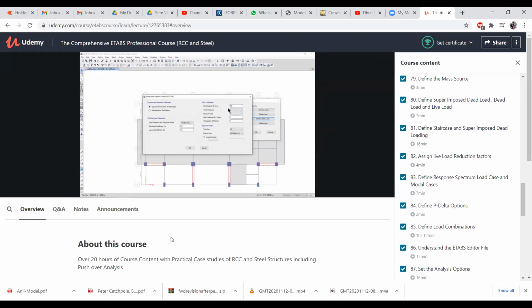All this looks very easy, like we can readily calculate and just input the data and ETABS will calculate the load automatically. But it is just like a black box, which I will never recommend, because we never have full control over the loads that will be generated by the ETABS program. For example, if we take the exposure from shell objects option, this option will nullify and we can enter all this data here and ETABS will calculate automatically.